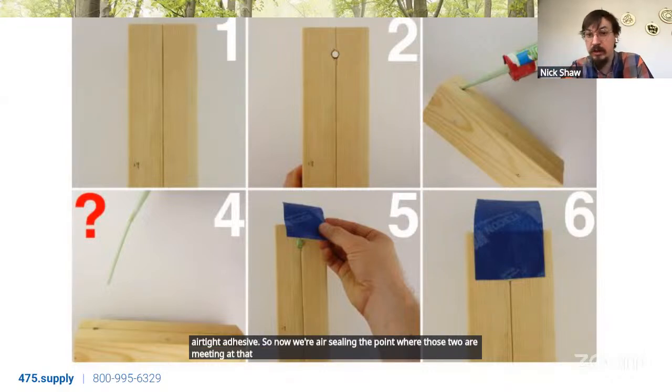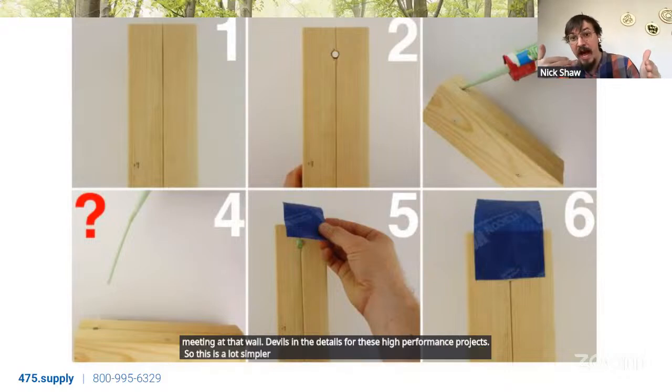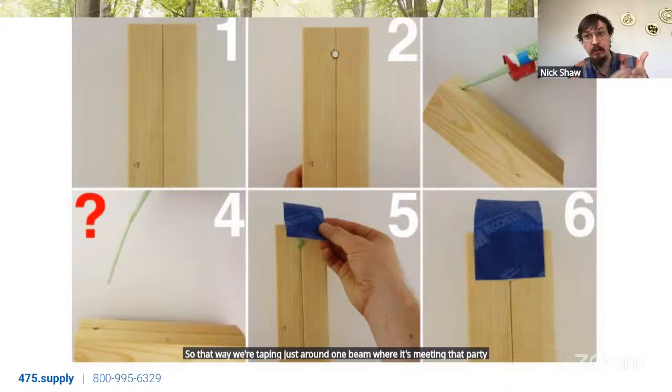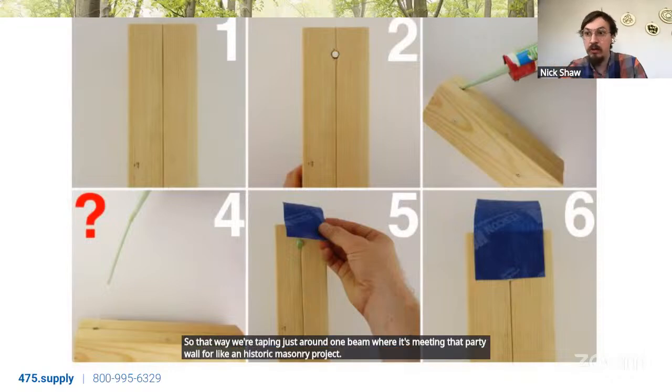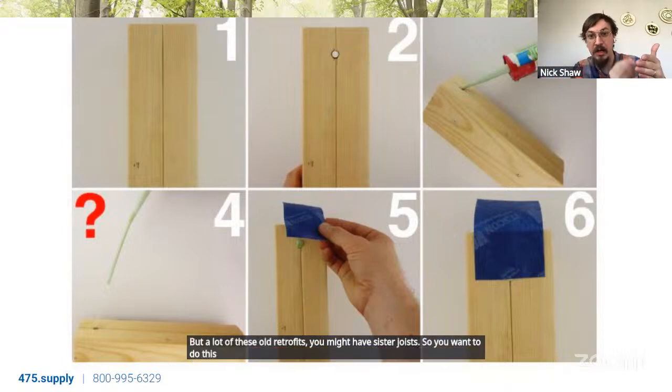Devil's in the details for these high performance projects. So this is a lot simpler if we're holding our sisters back. So that way we're taping just around one beam where it's meeting that party wall for like an historic masonry project. But a lot of these old retrofits, you might have sister joists. So you want to do this drill and fill it with an airtight adhesive where it's meeting that air barrier.